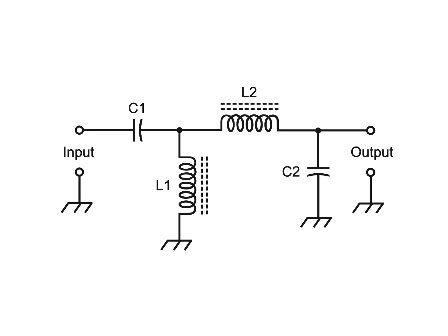Certainly, you must become familiar with the equipment you intend to repair, but after you have studied and understood the system's normal state of operation, you can use a schematic drawing to identify the general area of any future faults. By following this procedure, you can identify the most suspect individual components. Then all you have to do is find the suspect components in the physical system, get into the equipment with the appropriate test instrument, and check the suspect components one by one.